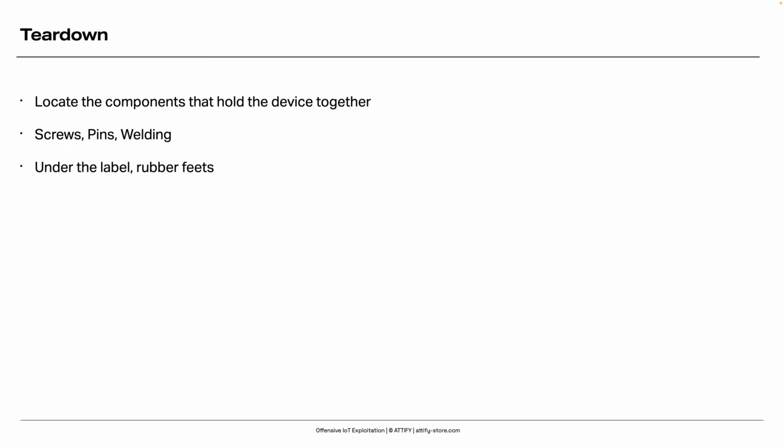And whenever you perform hardware exploitation, I would also very much recommend that you always have a set of two or more devices, because if you're opening up the device, there could be a possibility that the device has some sort of security in place, which might erase the flash if it's a very secure device, as soon as you open the device. So these kinds of things are something that you should be taking care of as well.